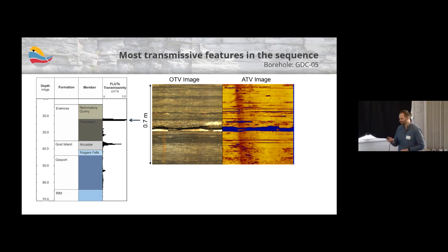But you can see plotted beside that, we have the transmissivity distribution along that borehole, those black bars. The laser pointer doesn't seem to work very well, at least I can't see it very well. This is the transmissivity distribution. So those black bars represent 1 foot intervals with transmissivity. So you can see, just to give you a sense of, there's a little bit of transmissivity along that full borehole, but there's certainly these strong features with much higher transmissivity.